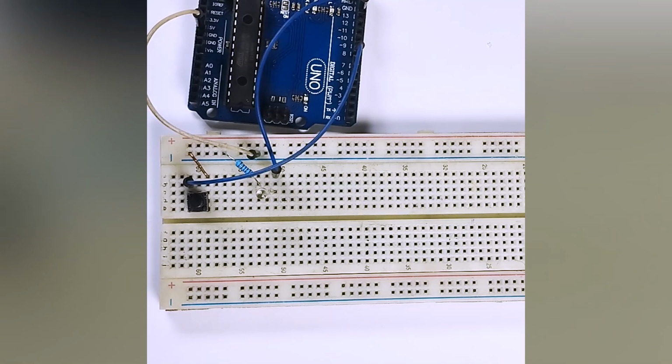Okay, so it's important to make them have a known voltage level. We want to give it a stable known voltage level, and since we want it to carry out a function whenever it senses 0 volts on pin 8, let's make pin 8 always high. So when we send a low to pin 8, it will sense it. One way to do it is to connect a pull-up resistor to pin 8.